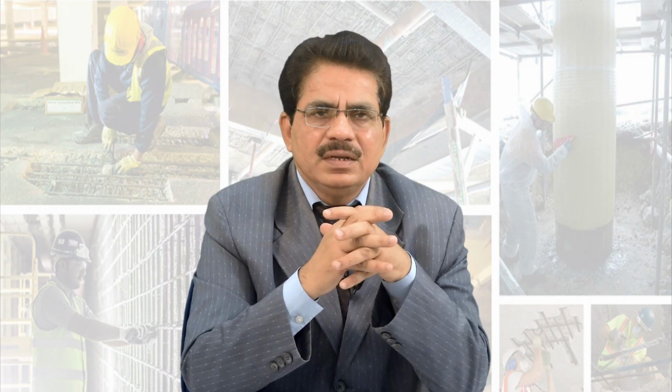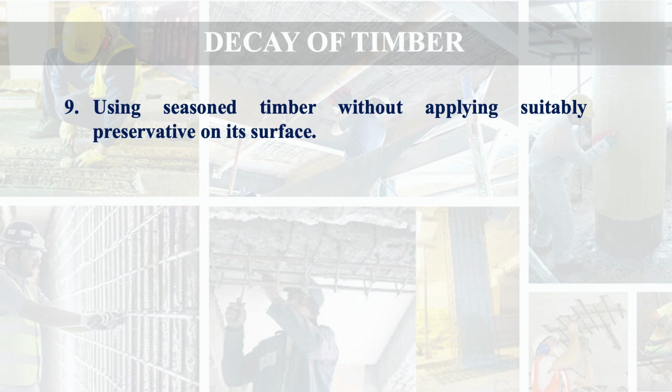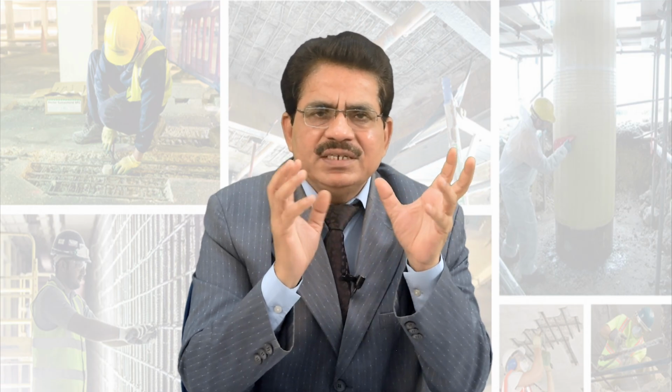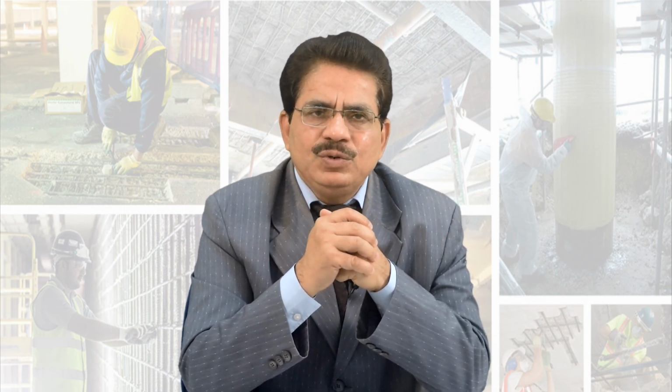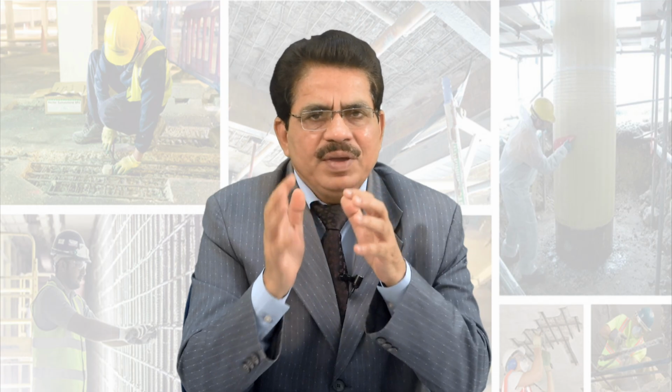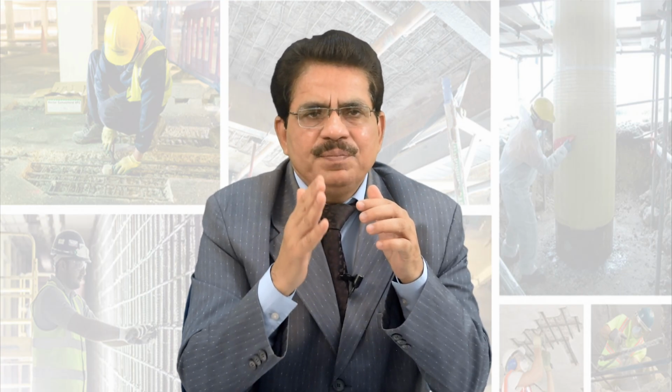Then using seasoned timber without applying suitable preservative on its surface. Here you look that only using the seasoned timber is not enough to ensure a long life of the timber. Even the seasoned timber may be attacked by insects and fungi. So to preserve it, to make it safe, we have to apply preservatives on the surface of the seasoned timber.